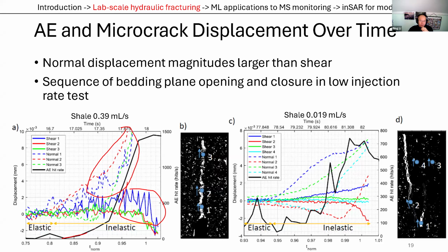And then comparing it to the acoustic emissions, in this case, they occur roughly at the same time. The acoustic emissions don't really precede the deformations in this case, and we posit that's because, once again, shale tends to be a lot more aseismic. It tends to be a lot more rate strengthening. So because our detection threshold for the acoustic emissions is a static value, we're only able to detect larger magnitudes of acoustic emission events in the shale, essentially.